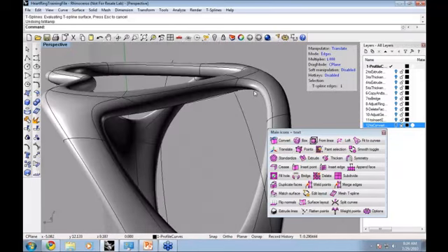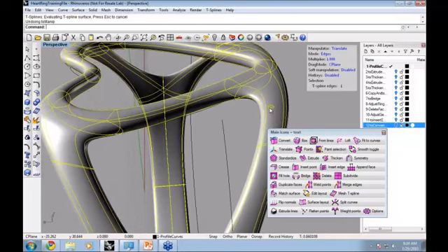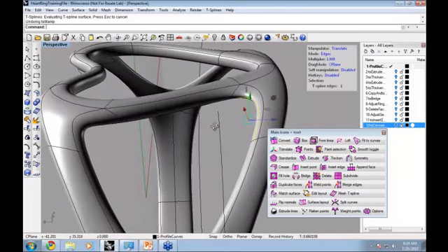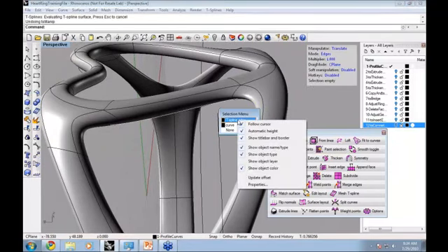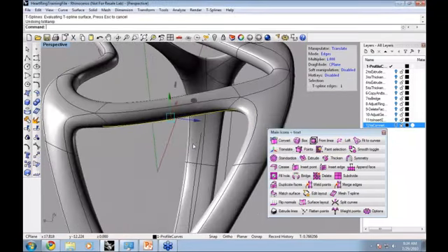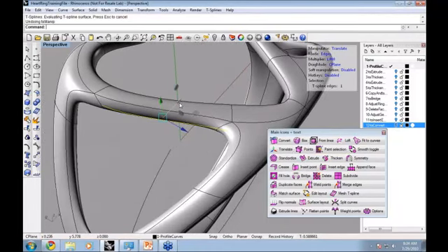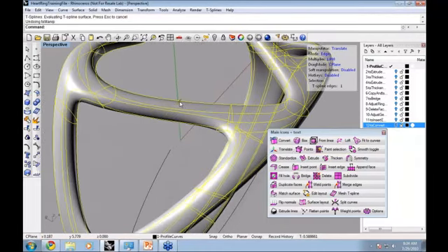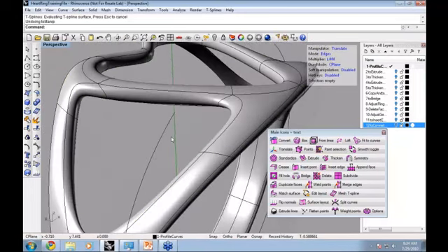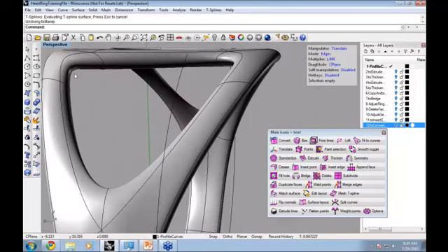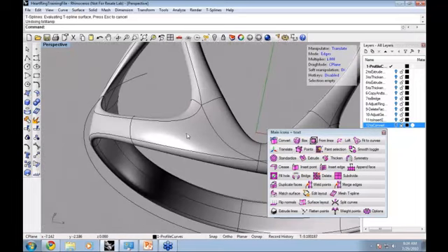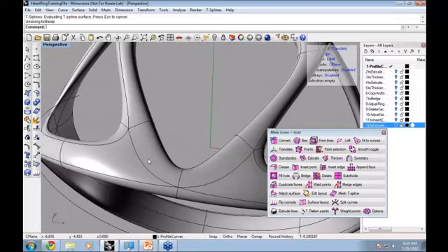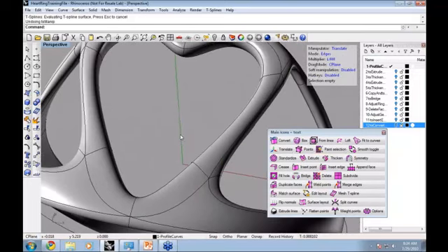And again, these are maybe the two biggest reasons why I think you might consider using T-splines. One is that you can really design while you model. After I get this ring put together, I can explore different variations just by tweaking the surface. The other reason to use T-splines is that all of these transitions and blends just come as part of the T-spline surface. So anything that you want to blend smoothly together, just merge or bridge it, and it will be a smooth transition.